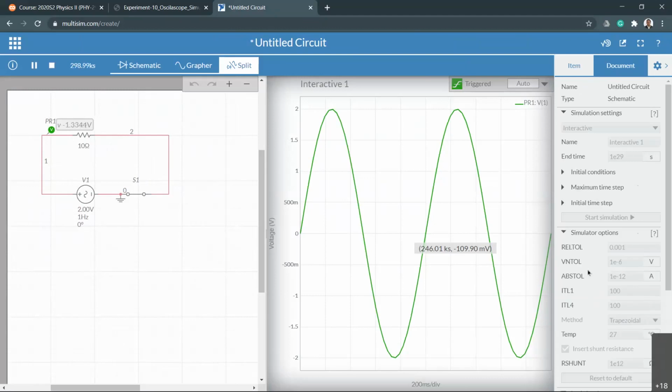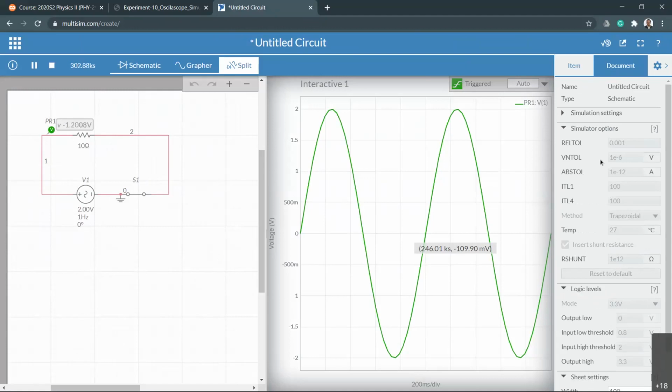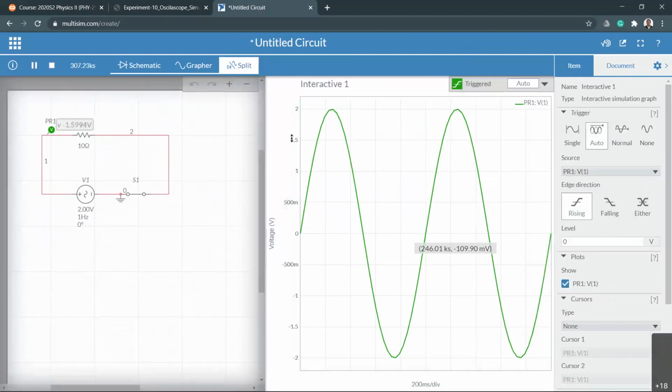There are a lot of different selection tools. All you have to do is click on the selection tool and see whether it is hiding there, okay? So you can actually find it out. That's very simple. For example, if you want to find the operation configuration tool for the y-axis, just click on the y-axis here. Bring the cursor, click on there, then that will automatically appear. If you want to find the X, click on there, then you will get that automatically.